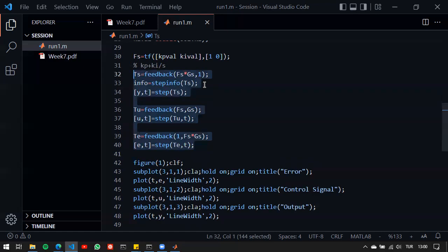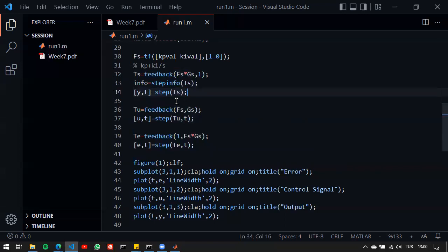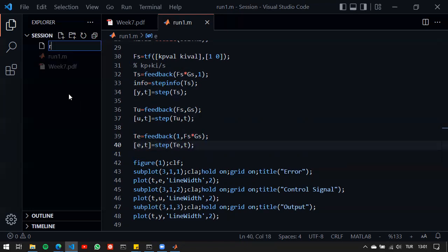Again, you can use Simulink, but I'll use something different in order to showcase that it is possible to use MATLAB like that. And it might be a bit more advantageous in that case. We'll see and talk about that. So in order to do such a thing, we need to use MATLAB and the fact that we can basically simulate control systems using just plain difference equations.